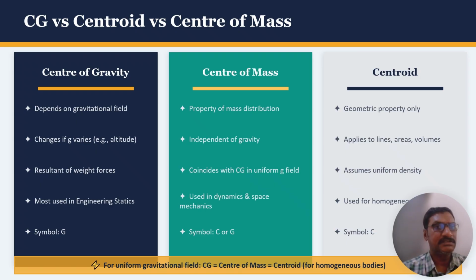Now the center of mass. The center of mass is a purely mechanical concept based on mass distribution alone. It has absolutely nothing to do with gravity. So if you are designing a satellite orbiting in space where there is microgravity, the satellite still has a center of mass. The center of mass is the weighted average position of all the mass in the entire body. It is the point that moves as if all the mass were concentrated there when a force is applied.